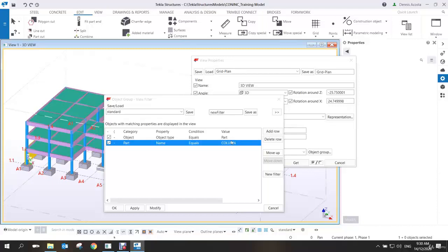And then, I have my first filter. This is my first filter of many. Why of many? Because I need to create the filter for a different part name. Okay? So, in this case, I'm going to type here, save as what? So, let's say you put your name. Let's say, for me, I put ned_column_filter. Okay? And then save. Save as.